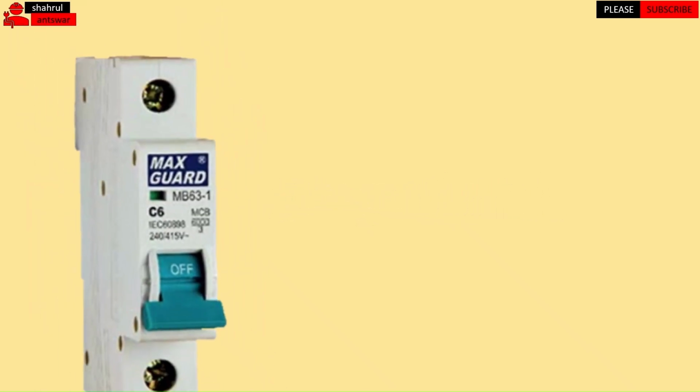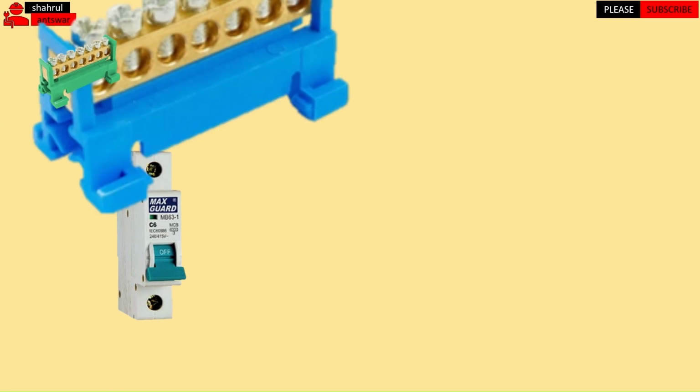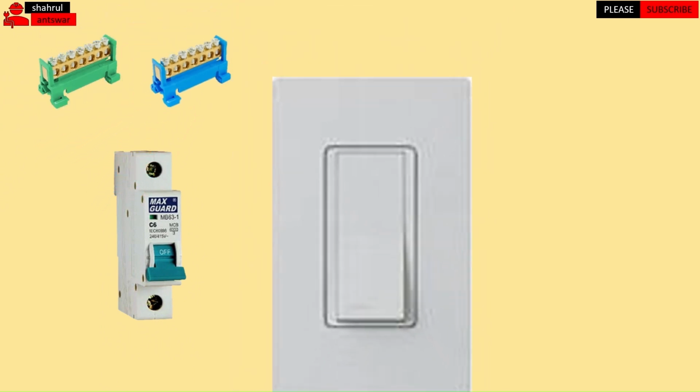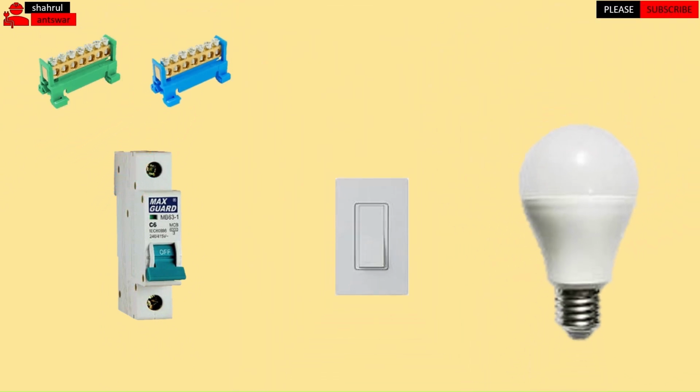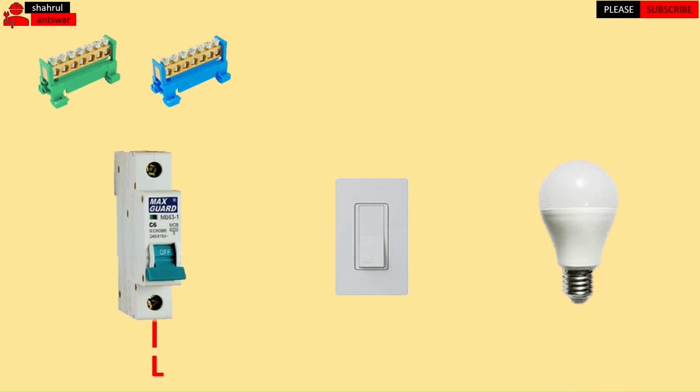MCB with the current rating of 6 ampere is used in this circuit. This circuit also needs a single pole switch and a bulb. Cable with a size of 1.5 millimeters square is used within this circuit. The connection shown is one point of light controlled by a one-way switch.